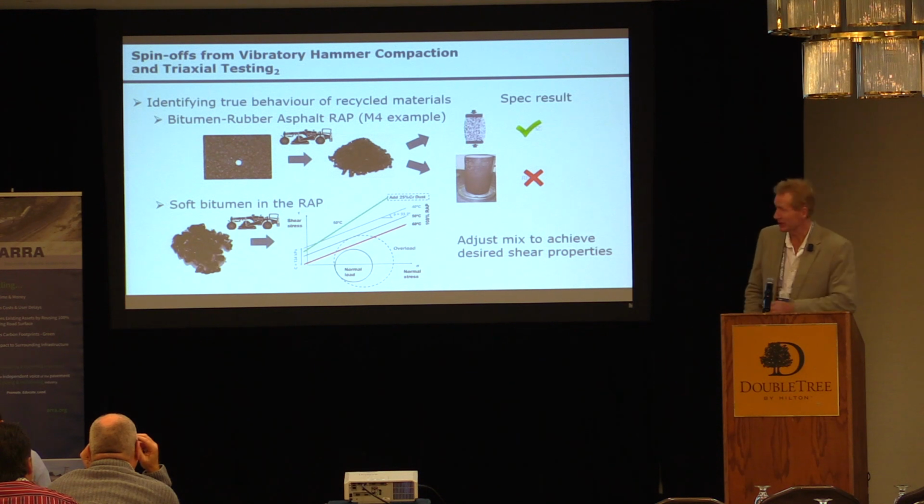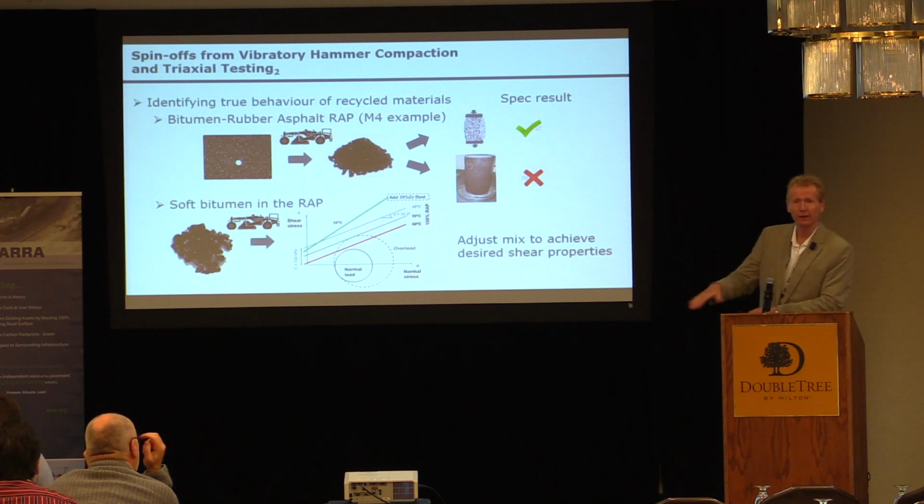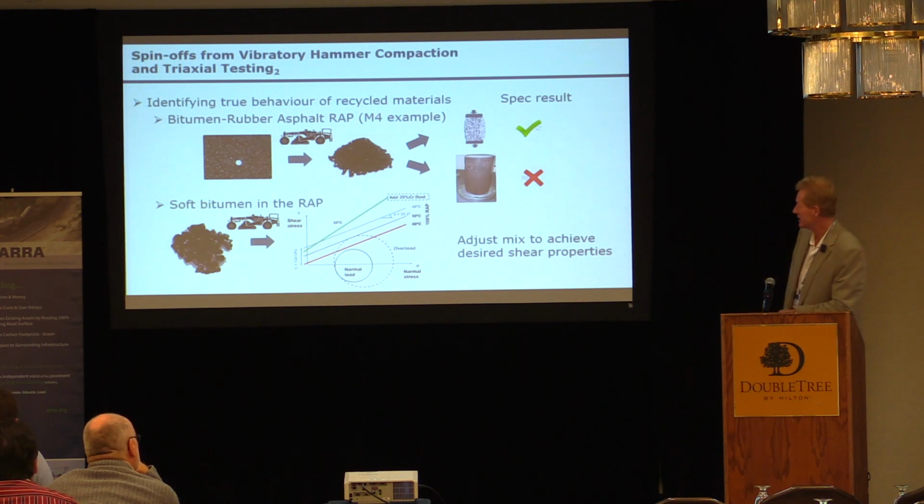When we did the triaxial tests, you can see we took temperature into account, because in this place it was not uncommon to have temperatures in the road, in your thick layer, of over 50 degrees. And as one can see, 40, 50, 60 has an influence on that failure envelope.